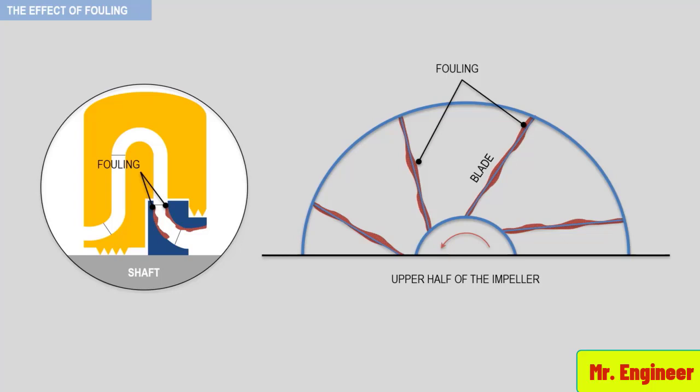Impeller fouling is defined as the accumulation of debris in the impeller or blade passages that reduces the flow area and roughens the surface finish. The distribution of the foulant on the impeller or blade row is non-uniform and usually changes with time. Flow patterns within the impeller or blade cause unequal distribution. In addition, the forces exerted on the foulant cause it to chip off with time as it becomes dry and brittle. This results in a change in rotor balance and a change in performance of the compressor, as we will see in a later video.